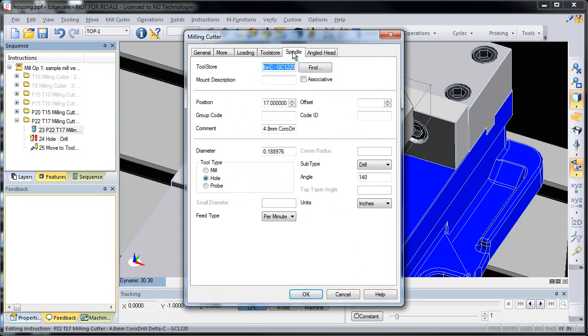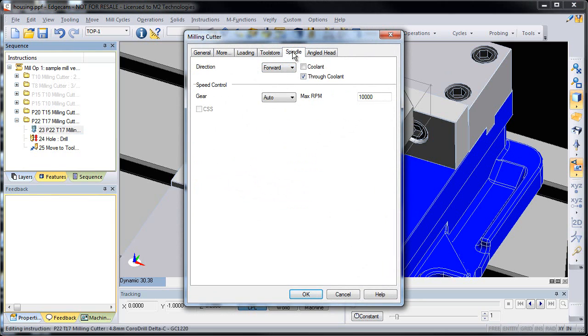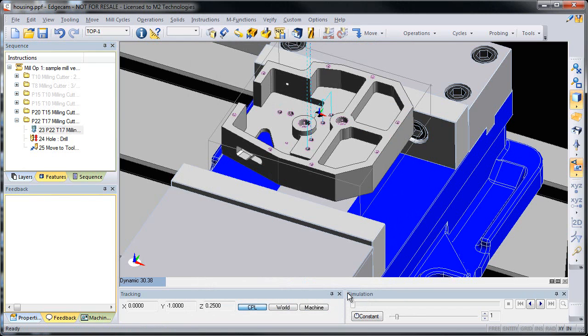This is very helpful. The maximum spindle speed values used for speed capping are assigned in the CodeWizard post. They can also be modified for a specific tool using the spindle page. Notice that you can set the gear range and the maximum spindle speed values. Please note that this capability requires a post processor created using adaptive lathe and mill templates.